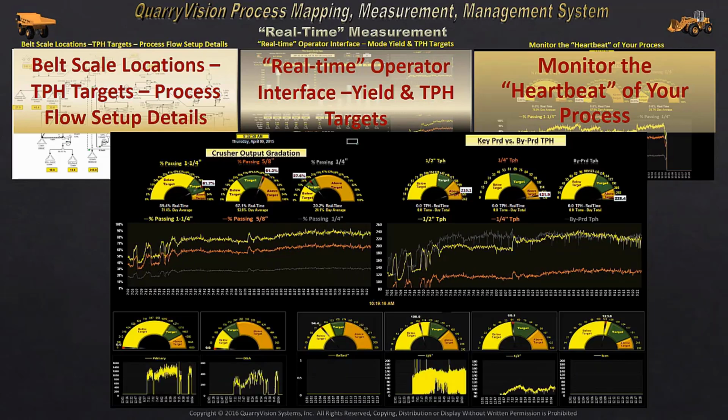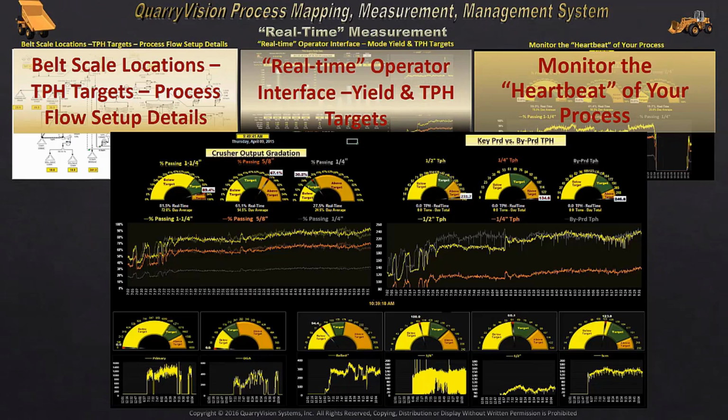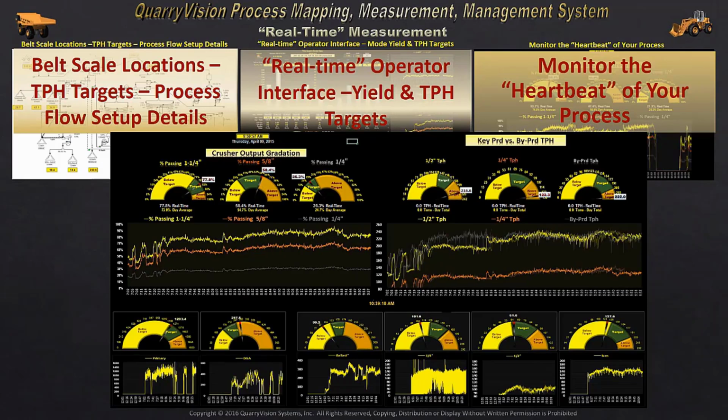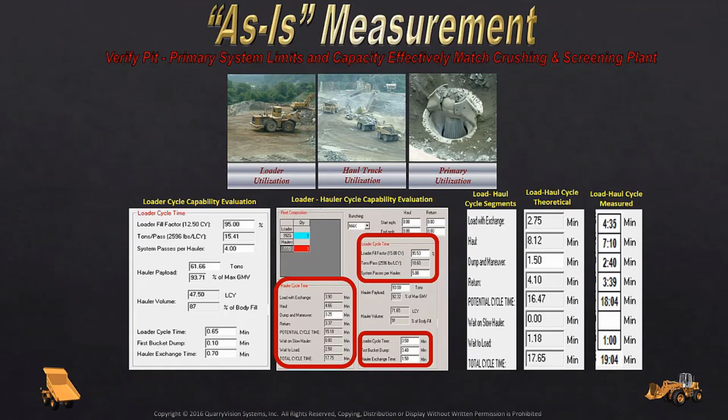All of this having been established, setting valid performance targets then comes down to ensuring that the plant can be reliably fed at rates determined to be capable, within its various operating modes. This requires assessment of pit capacity and surge pile management practices, including evaluating both load haul rate consistency, and potential feed gradation segregation if surge pile drawdown has potential to become a crusher capacity factor.